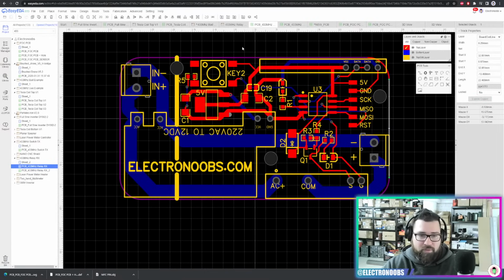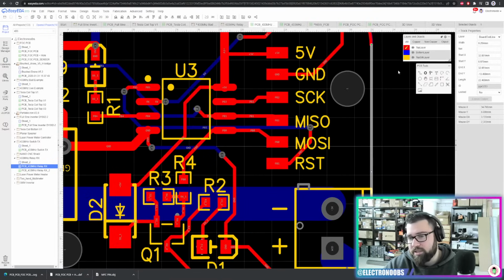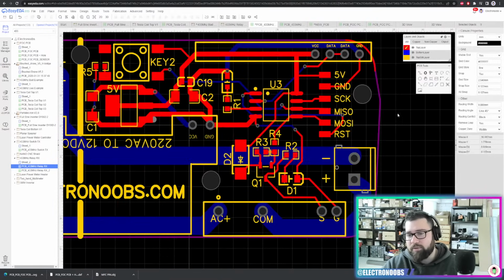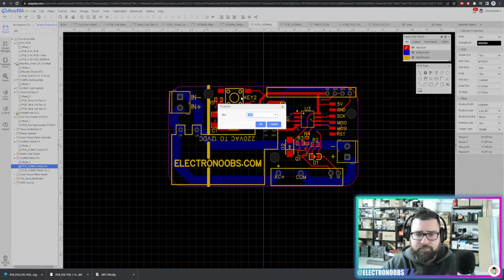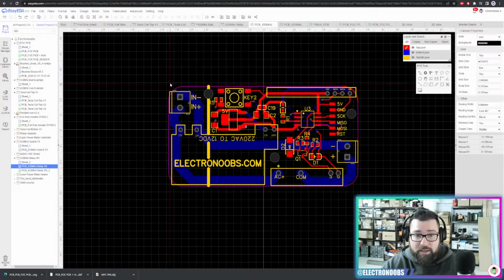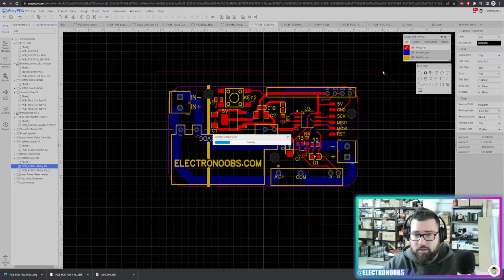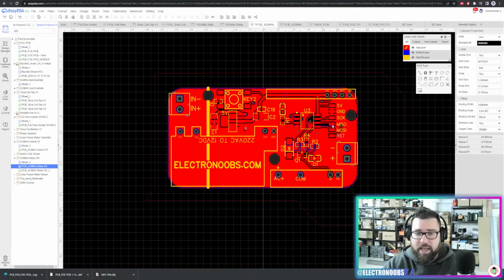Make the shape of the PCB as you want it by just double clicking the pad and moving the pads around, and that will give a unique shape to your PCB. And once you have it, the final part should also be adding a copper plane, but in this case, since it's working with high voltage, I don't want to do that. But if you want, just click this button here, select what kind of plane you want to add. In this case, I will add the ground plane. Just select the area like this, and as you can see, that will automatically add a copper plane.